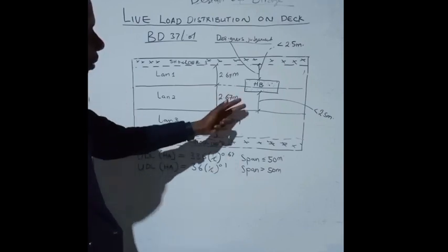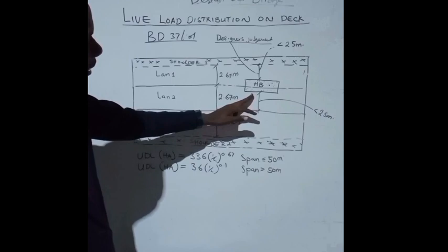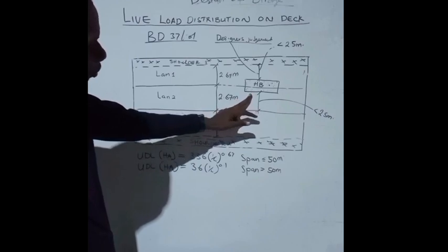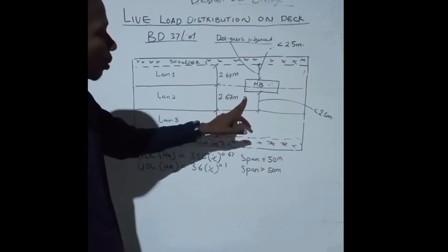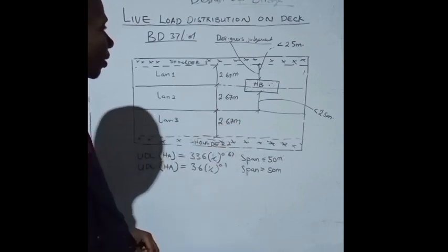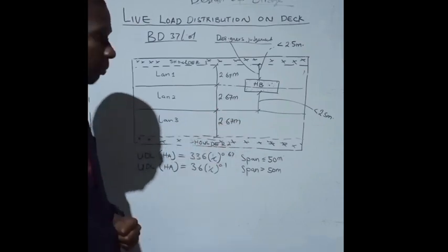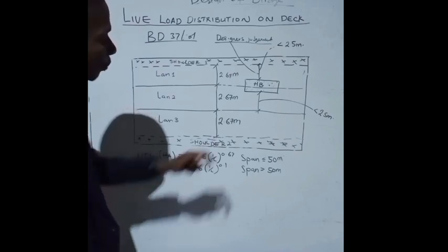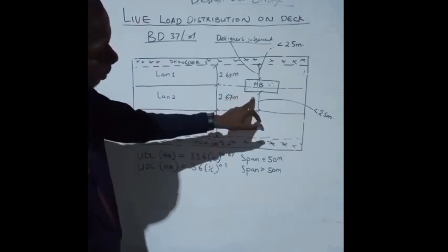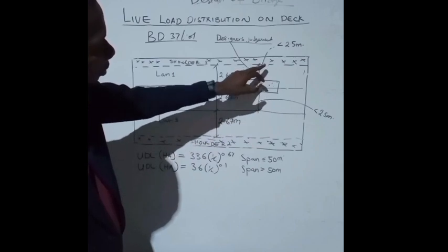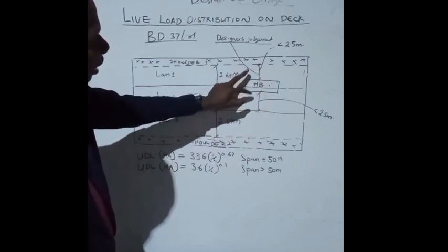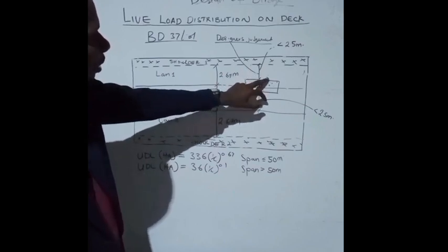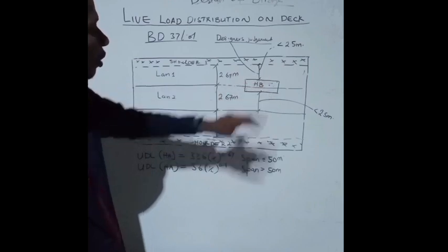If you look at it critically, you see that the HB load, like what we have on the board, straddles between 2 national lanes. There are 2 conditions attached to this in the BD document, just as it was in BS 5400 part 2. The first thing you discover is that, according to the BD document, the HB vehicle is at the first lane closer to the shoulders.